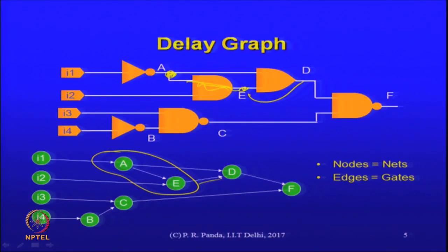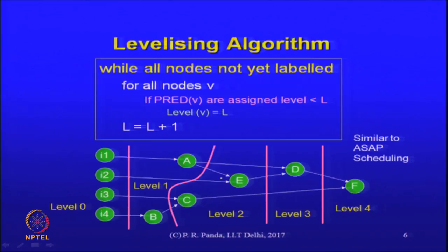There are delays associated with the nodes. As of now, we just said it is 1, but in general I can put any delay there, and that can be included in some appropriate way. A trivial levelizing algorithm is something that we can start with. Let us just assign levels. Levels are useful because they tell us when a signal arrives at some inputs or some output. This is a DAG kind of a circuit anyway, so I should be able to assign these levels.